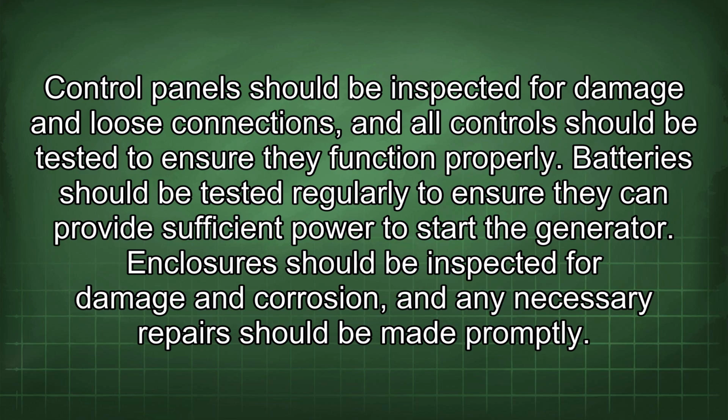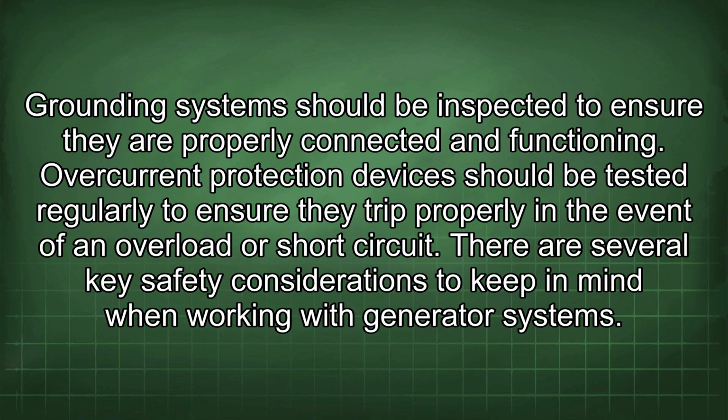Enclosures should be inspected for damage and corrosion, and any necessary repairs should be made promptly. Grounding systems should be inspected to ensure they are properly connected and functioning. Overcurrent protection devices should be tested regularly to ensure they trip properly in the event of an overload or short circuit.